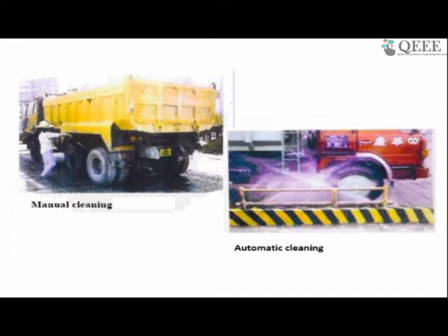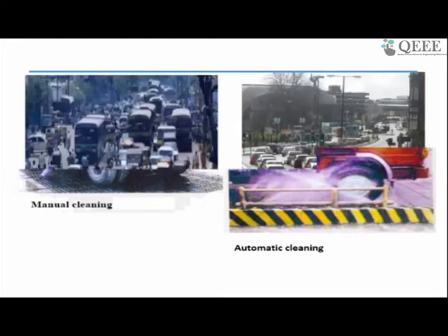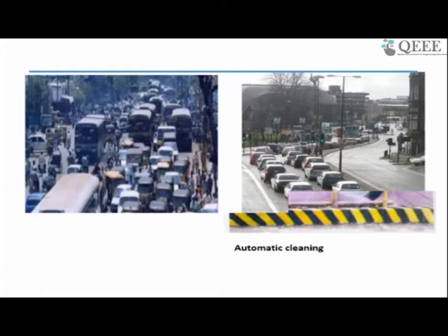Clean them before they go out from the site. So one is manual cleaning, and the other one is mechanical cleaning, where when the vehicle comes near the platform, a jet of water is automatically flushed on it, and both the vehicle body and the tires will be cleaned.